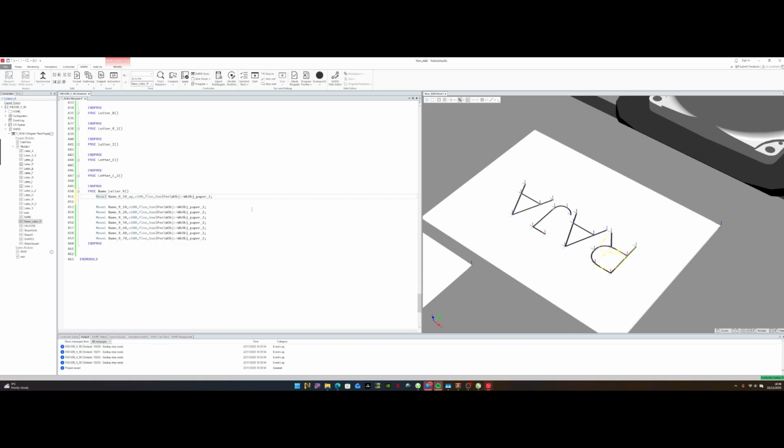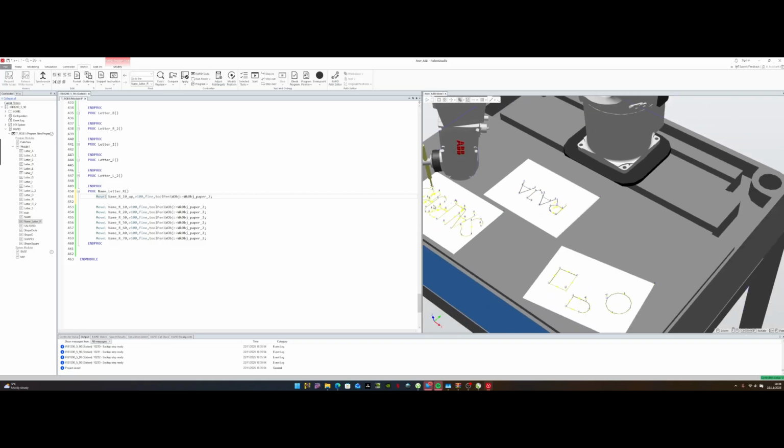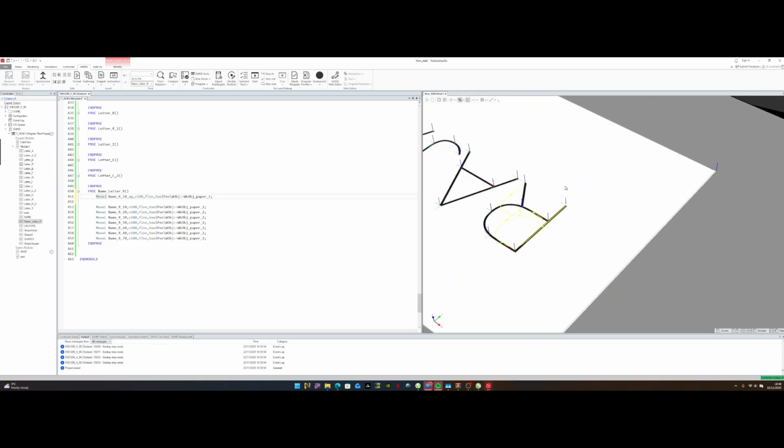And now that I've done this, what's going to happen is the robot, from wherever it is, if it needs to execute R, it will just jog freely to a target that's going to be hovering over R here. For now, we can't see the target yet, but you will see it. Then when it gets there, it will then do a move L, which is a linear, to the first target, move L to the second target, move L to the third.